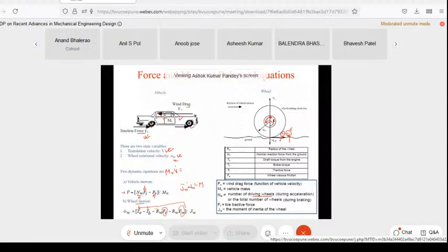After you write both the equations, what you need to do is linearize them. Whenever we have a set of non-linear equations like this, they are all non-linear: Fv will be directly proportional to v square. So we first linearize them. That will give you the Jacobian, and then we find the eigenvalues of the Jacobian. If the real part of these lambdas turns out to be less than 0, we say that our system is under a stable condition, and if it is greater than 0, we say that it is unstable.